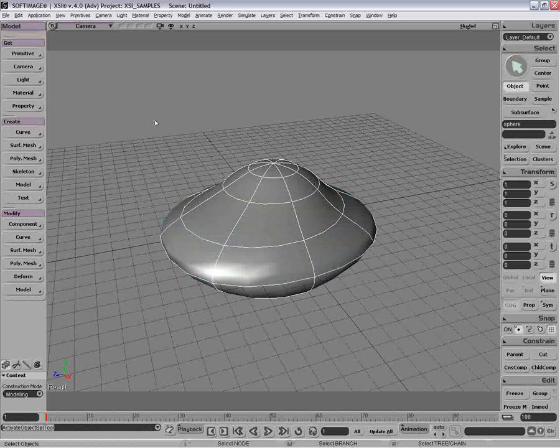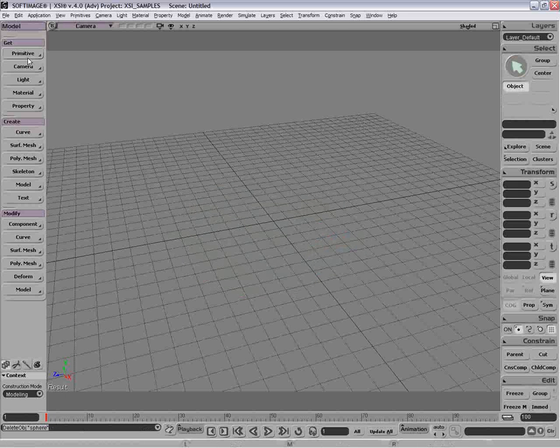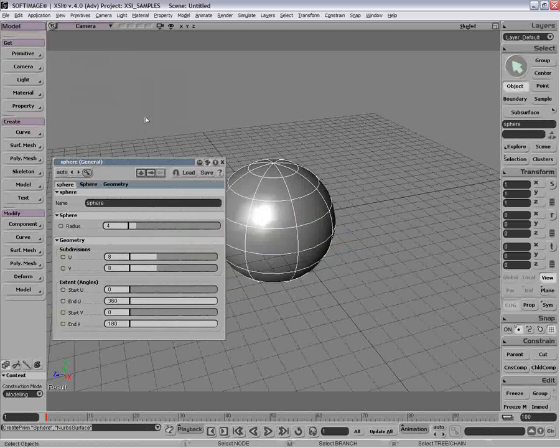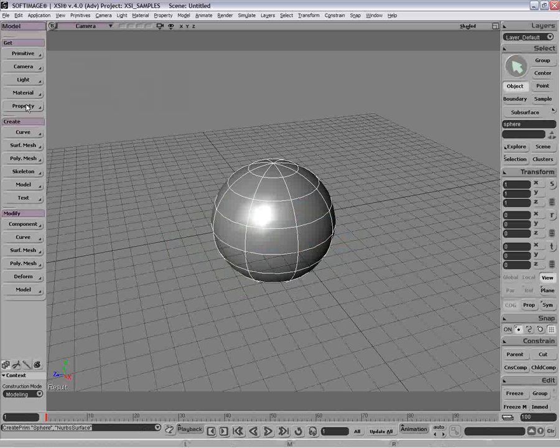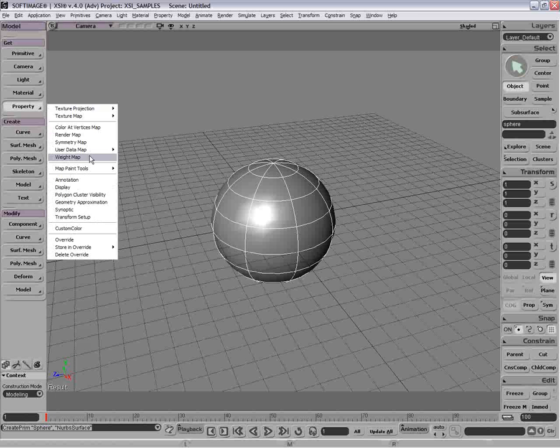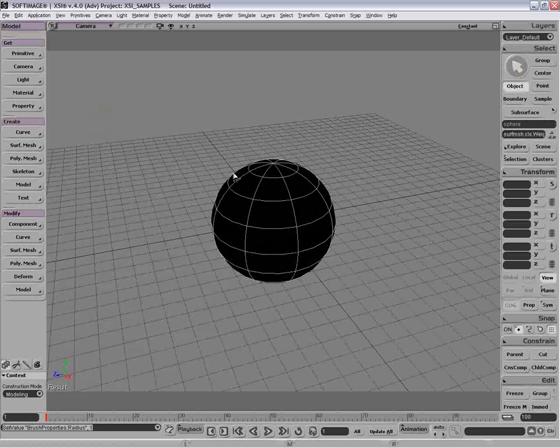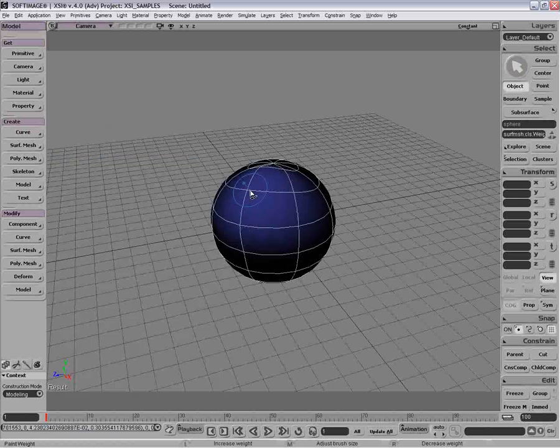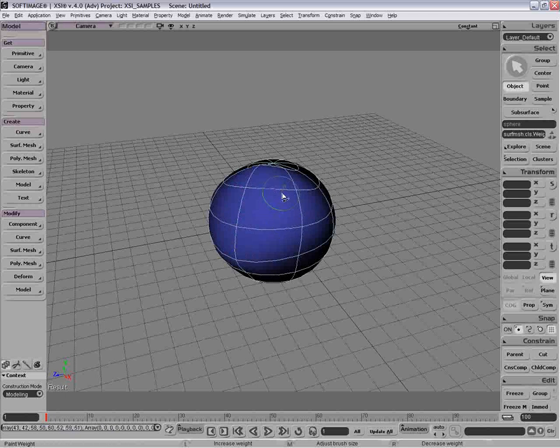And while we're talking about brushes and all of that sort of thing, let's talk about one more type of deformer in that area that's quite useful, but it's on its own. You can either go in here and it's under Deformers Push, but you can also directly connect it with a weight map under the Map Paint Tools Paint Push tool. So you grab that, and what it allows you to do is model your object a little bit with your paintbrush.